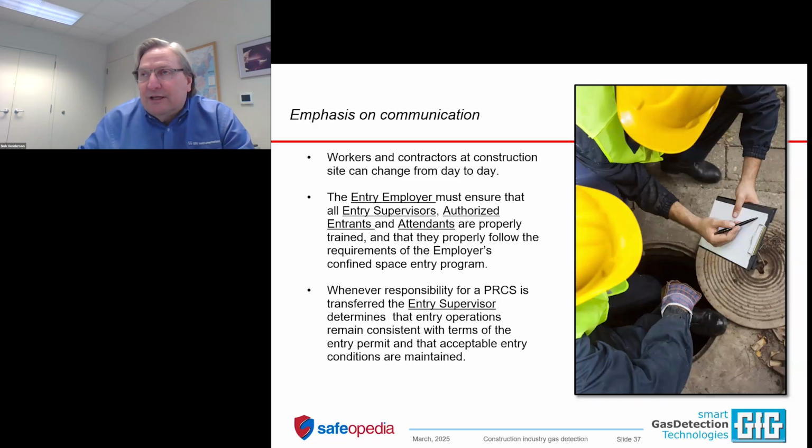you absolutely need to have, in an open confined space, somebody in charge, and there has to be a formalized way of trading responsibility to a new person. If the shift is over for the one entry supervisor, there has to be a good track of who is in charge of that confined space any time that the confined space is open.